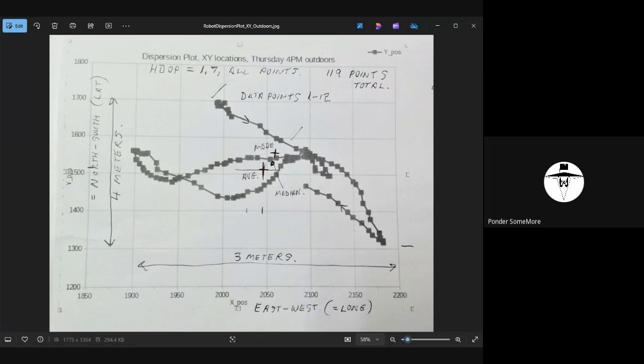So what I'm saying is, in this case, if I want a certain degree of certainty, I'm just guessing off the top of my head, I want to be within 10 degrees, and I see that there's a 3 meter radius of uncertainty around where I actually am versus what it's telling me, then I might want to be 50 meters away from this original location, through odometry, before I say I'm far enough away to believe the angle difference between those two locations.